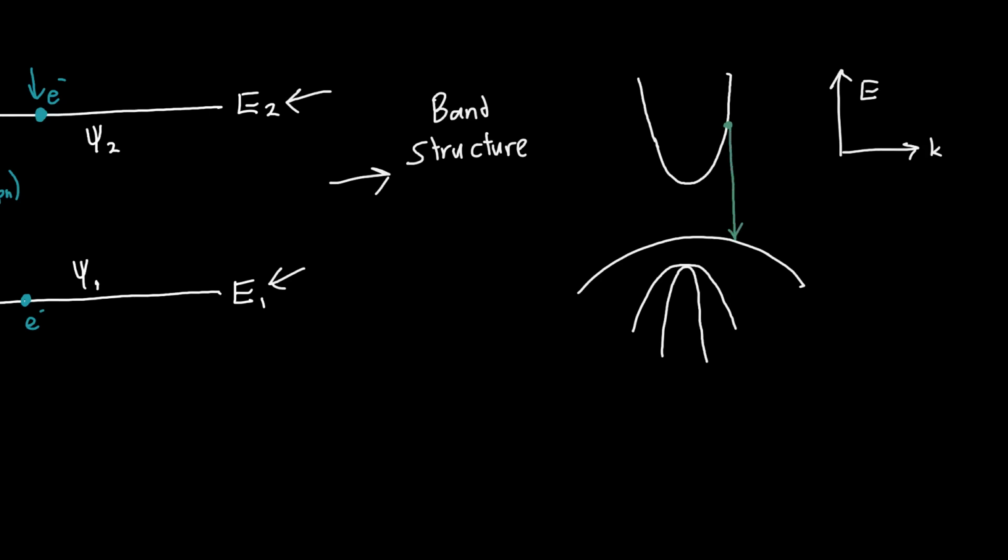this material. So a photon, for example, if we've got an electron up here and a hole down here, we're allowed to emit a photon as these two recombine with each other. So this is the conduction band, and these are the various valence bands. And so once we figure out where photons are allowed to go between, we'll also analyze things like quasi-Fermi levels, so EFC and EFV, and how these affect our absorption, or how these affect our band diagrams and how we go about representing them.